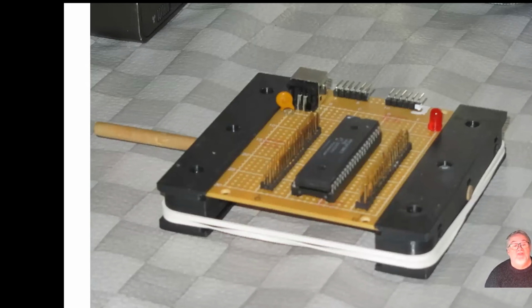Now, the 5 volts USB from a motherboard is supposed to fuse at about half an amp, or it's supposed to stop at half an amp, but I don't particularly trust that. So I've got a 200 milliamp 6 volt polyfuse in there, because on the PIC circuit, the pins for the supply and the pin for the 0 volts are right next to each other. And the pin for the 0 volts will have something like a scope probe or a meter on it, and it's waggling about, and it's liable to touch an input pin or touch a supply pin,